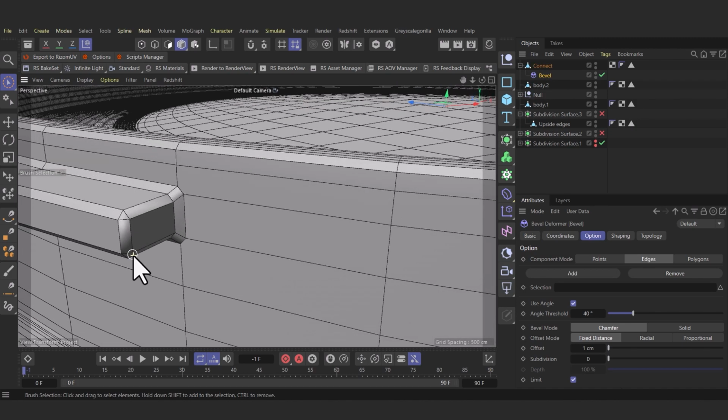Finally, I use a deformer called bevel to soften the edges of my work. By changing the offset and subdivision quantities, you can reach the desired curvature. But as you've noticed so far, more connections equals more softness, and conversely, more effort to convert them into quadrilateral polygons. So use it wisely.